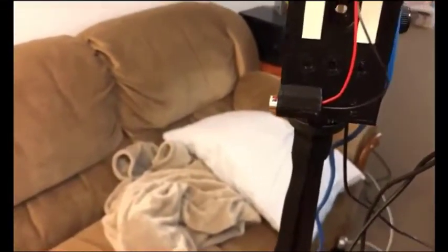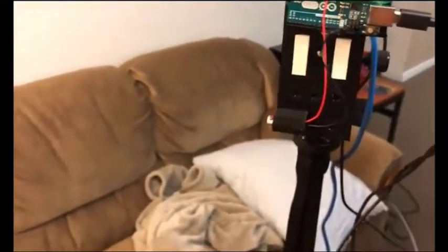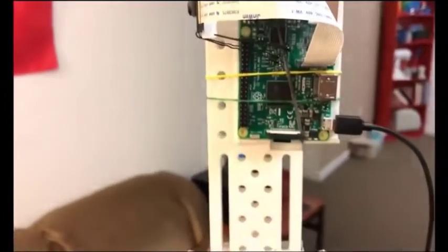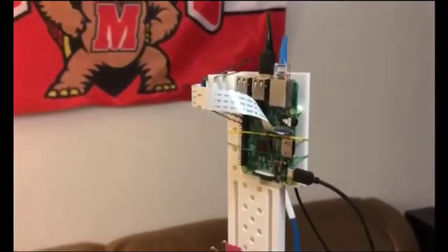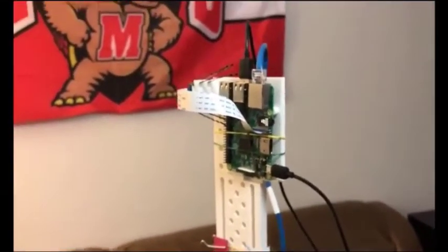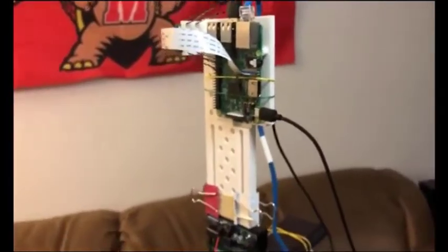And so just going over the basic layout of the LiDAR again, the red line laser acts as a transmitter, sends out photons to an object, and the photons come back and are received by this camera. That camera takes the data and inputs it into the software of the Raspberry Pi, which we're using Python for in this class. We can do a variety of things with the camera images and the pixels that we receive and manipulate the data from there.